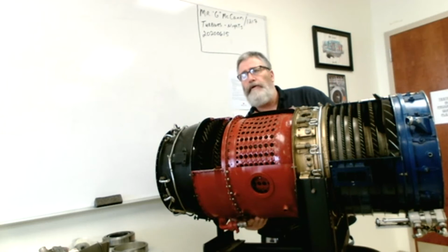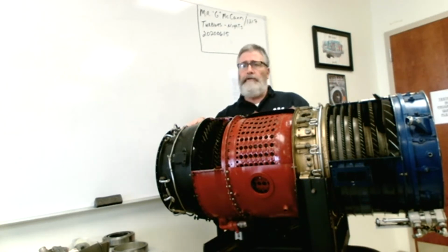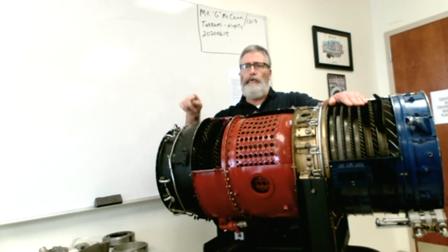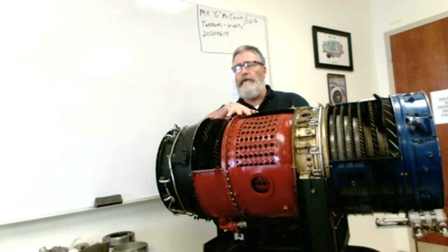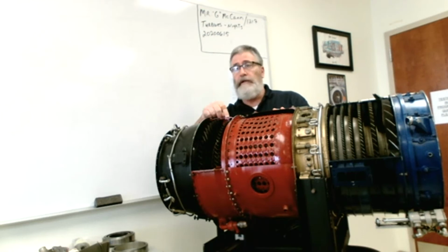The drain valve is very important. When an aircraft is shut off, because the fuel pump is geared to the compressor side, as long as the compressor is spooling down, getting slower and slower, we're still pumping fuel into this engine. So when the pressure finally reduces after we've shut the engine off, the combustor dump valve or drain valve will open, and any excess fuel will dump either overboard on older aircraft, or it'll be recycled back to the fuel tank on more modern aircraft.